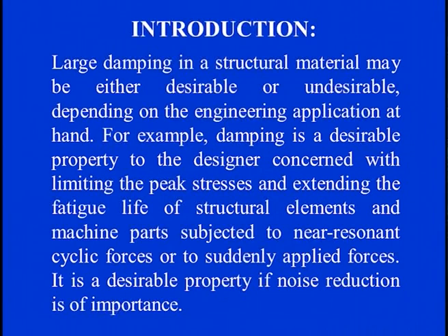And here we have to be very careful when such peak stresses are forming, we need to limit those which are very close to resonant cyclic forces or even any kind of impact loading, when there are abrupt changes, not only in the magnitude of the forces, but also in the direction in which they are applied to the system.